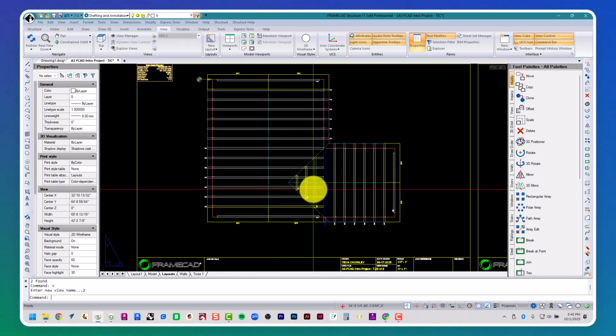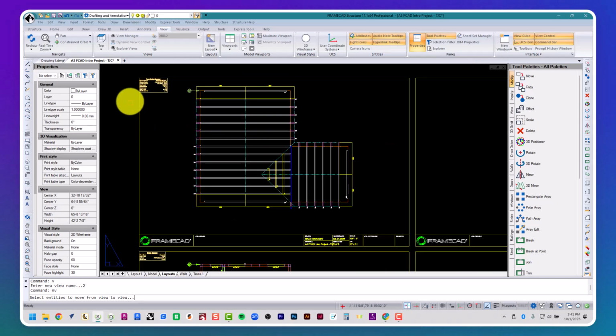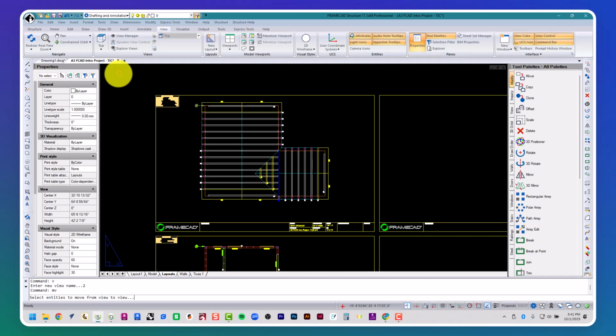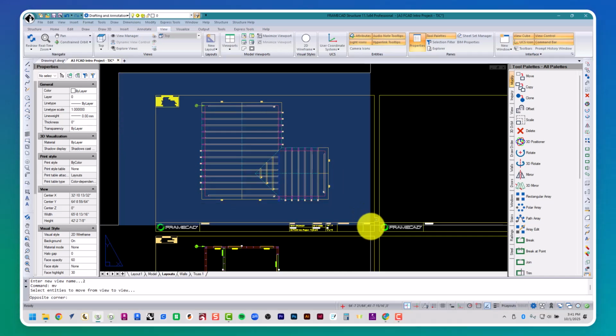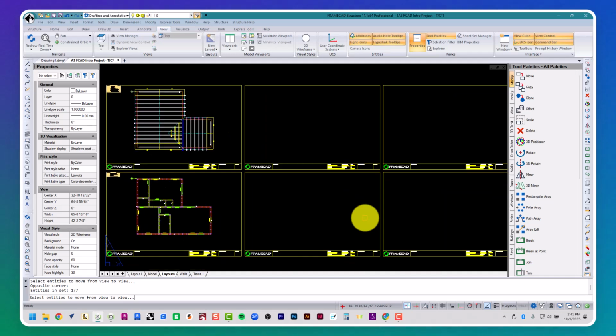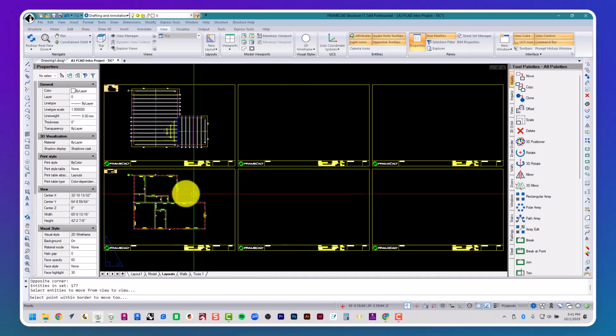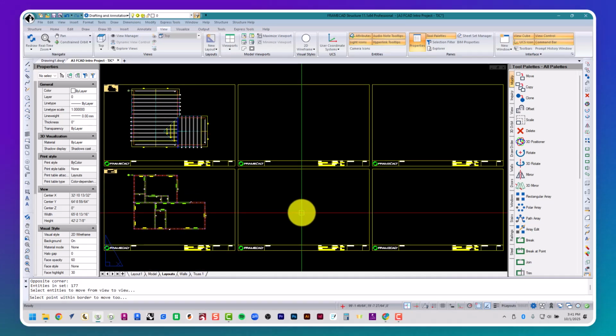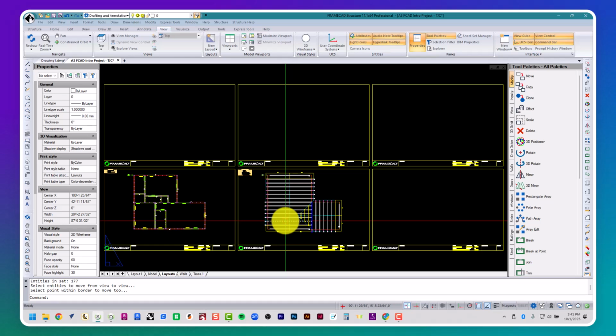Let's quick navigate to border number 2, V-enter to enter. We're going to type in MV for move view. We're going to select all the trusses, the reference point, the support line, roof lines, and the truss design summary in the top left corner. We're going to make a big selection window. So I'm going to zoom out, and I'm going to click way over here, and I'm going to click way over here. I'm going to press enter, and I'm going to put it on border number 3. So 1, 2, 3 is right here. Click once, and everything will move over.